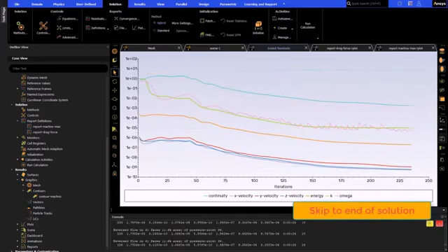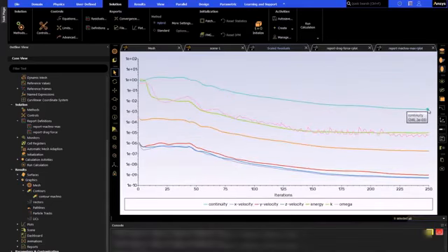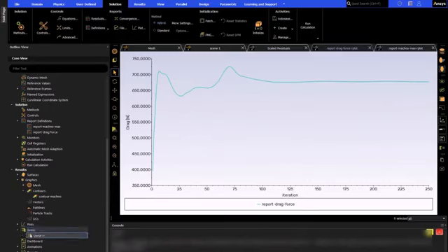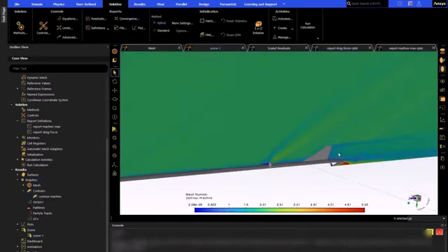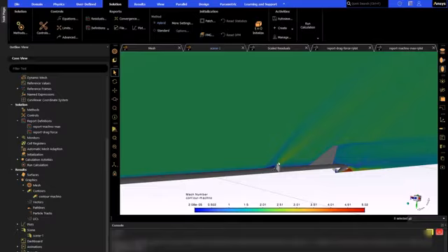Once the simulation is complete, we can post-process the results as usual. With the existing graphics objects, the shock structure caused by the air brakes is evident, and the new drag force can be computed in the flux report and compared to the original design.